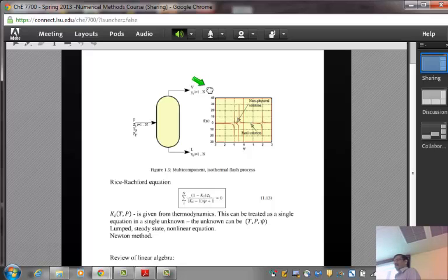So I have a mixture of 10 components in a vessel, at atmospheric pressure, and initially it is all liquid, and I keep increasing the temperature. I want to find that temperature where the first bubble comes up, because that's a vapor. I've given you the clue now, right? Bubble point. So the bubble point, the dew point calculations, they are all embedded in this model.